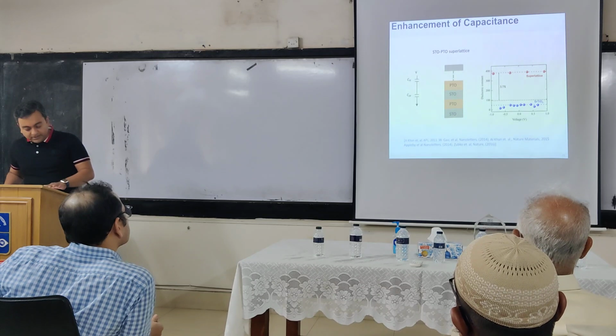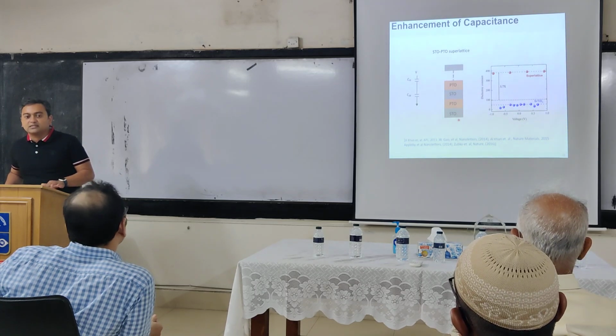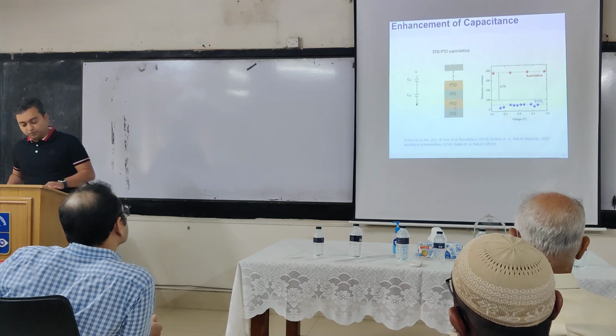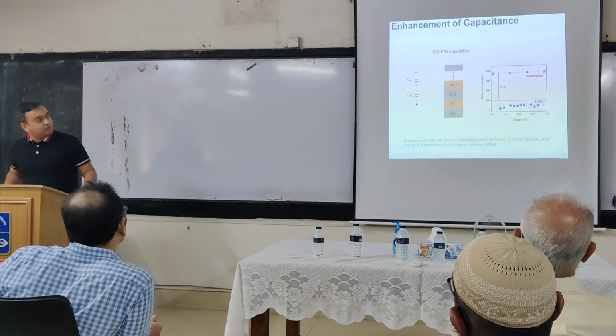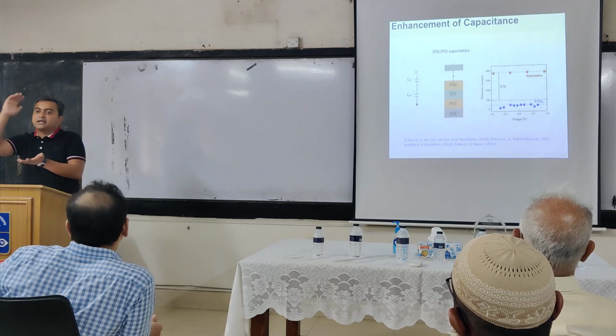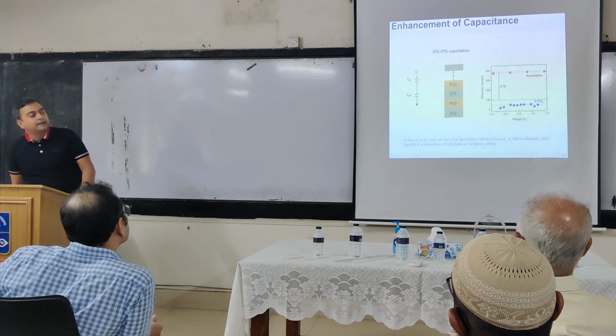Okay. So what we did is we created this series network, but it's a little bit complicated series network where we have multiple series capacitors. PTO is lead titanate and STO is strontium titanate. STO is a dielectric, PTO is a ferroelectric, and we put multiple of them together. And I can talk about why we did that. But in the end, it's ferroelectric and dielectric capacitors connected in series. Okay.